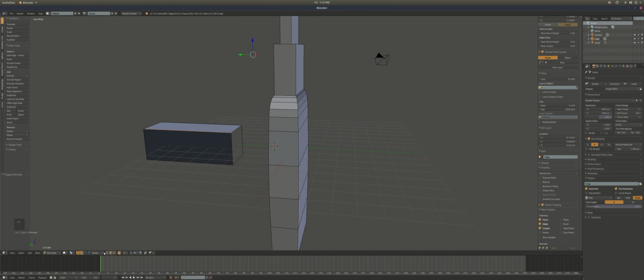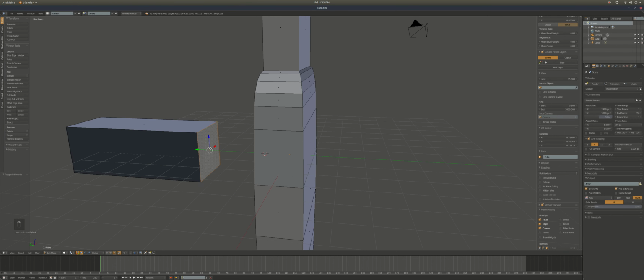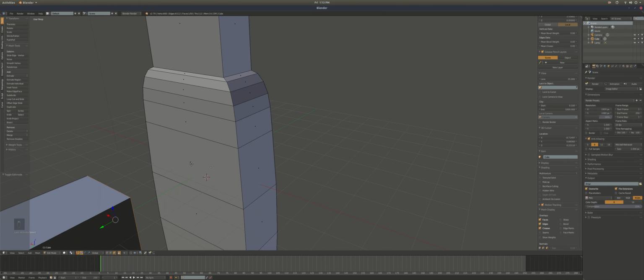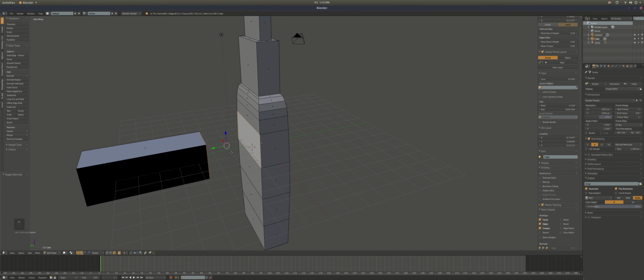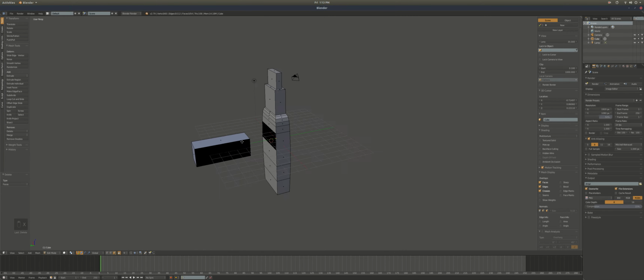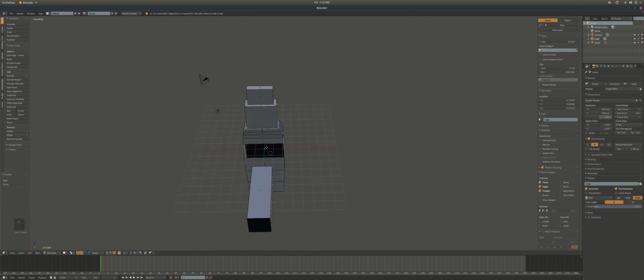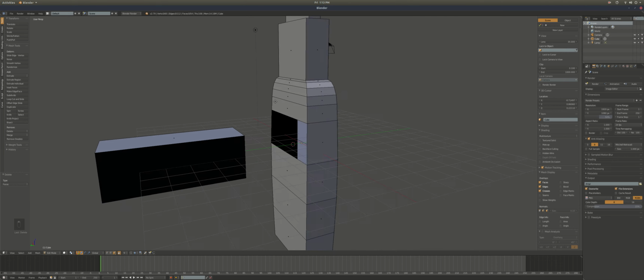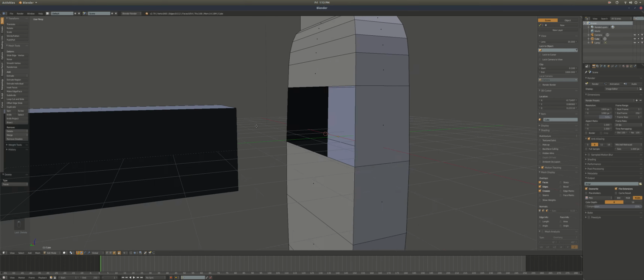But now that you're in edit mode, which you can go right here and do, click on your face, select this face, and you can hit X or delete. X will bring up the menu and just say, I want to delete those faces. And so that's really simple.